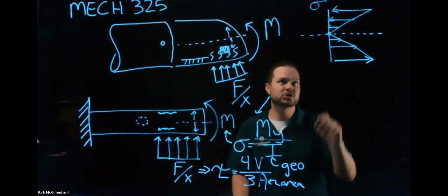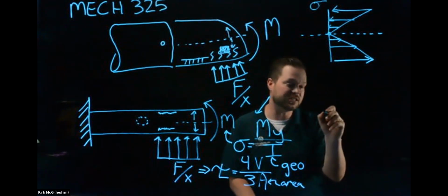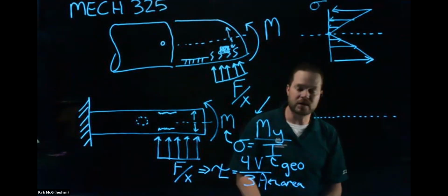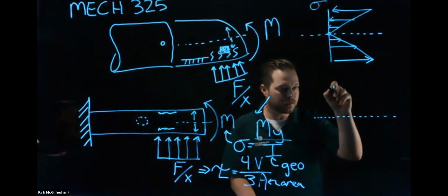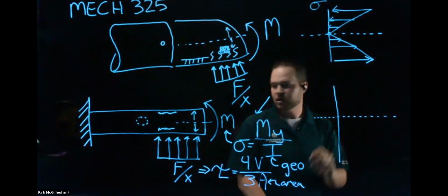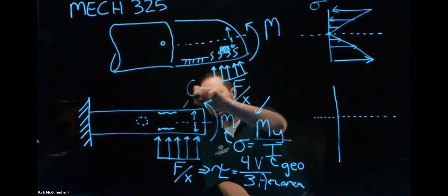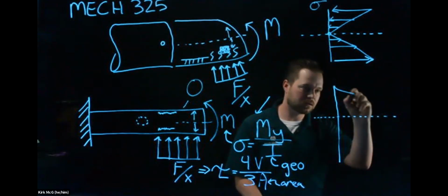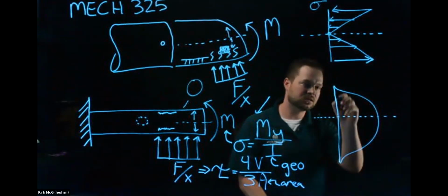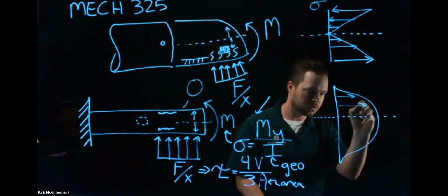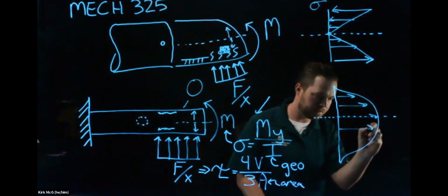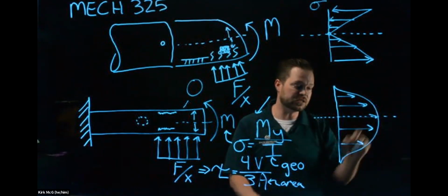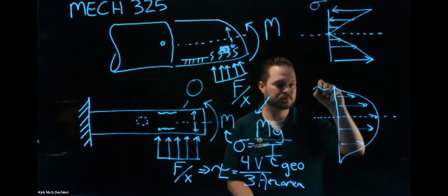Let's just look at this tau, this shear stress. So again, that has some kind of stress distribution. So again, let's do that as a function of, say, the middle part of our beam. Well, what that looks like, again, let's assume this is a circular cross-sectional area. It would look something like this. Where it's always in the same direction, but its magnitude changes with respect to depth.